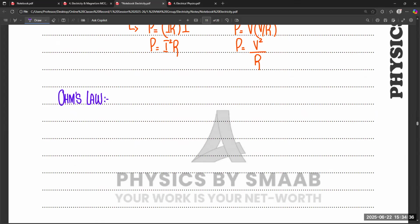So basically, Ohm's law tells you about the type of conductors in which the value of voltage and electric current are directly proportional. For example, if we use normal wire, or normal types of copper, iron or silver conductor, that will give you the concept of voltage and electric current both being directly proportional. But if we use different types of components like diode, filament, LDR, LED, these components will give you a different idea for voltage and electric current.